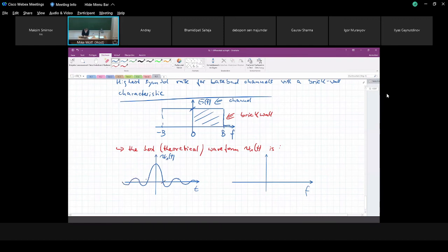And here we see exactly t, minus t, 2t, and so on. And here we would have 1 by square root of t. But this is not important. Important is that the zero crossings are exactly at multiples of our symbol interval, of our modulation interval.